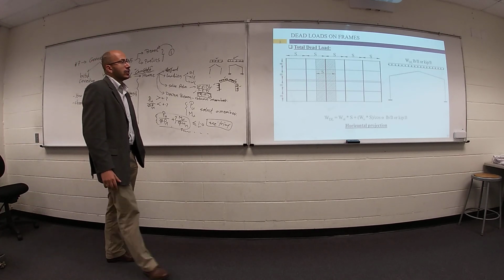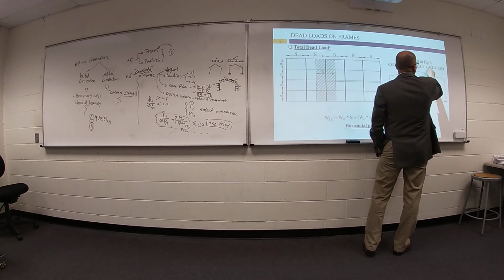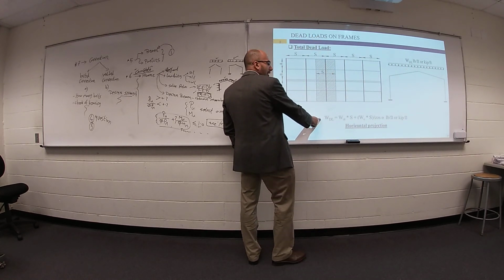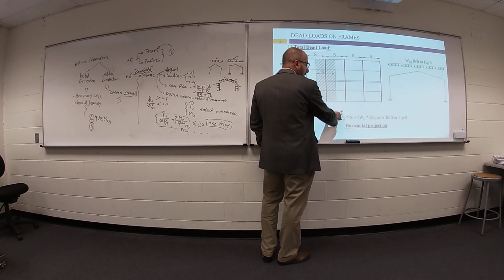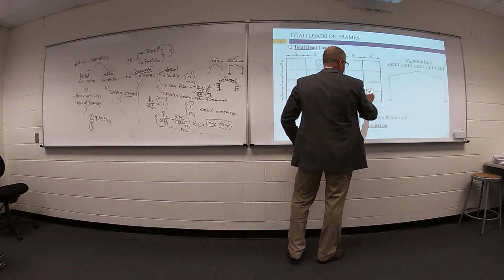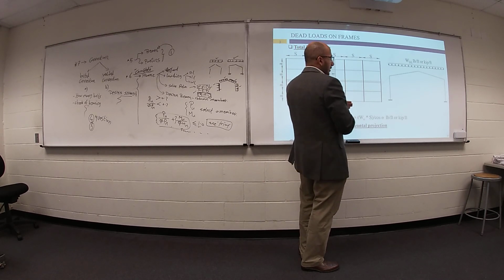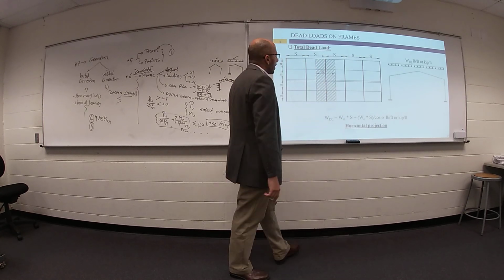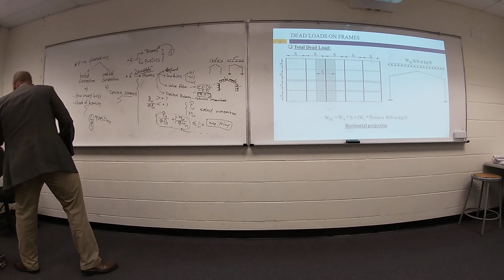So, if you would like to get your dead load as line distributed load, which is horizontal projection, go ahead and use this equation. First value, which is 100 to 200, select something in between, times S, spacing between each main system, plus the second value, which is covering corrugated sheet or slab, times S also, but divided by cosine theta. Your theta is this one.